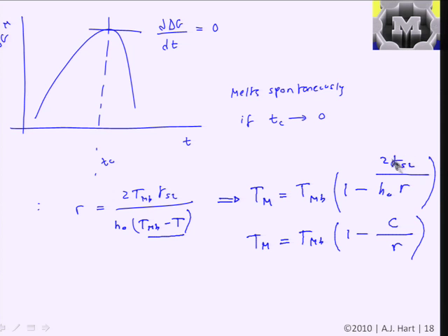Also, the value of this term increases as the surface energy of the solid-liquid interface increases, and it decreases as the latent heat, or the heat required to melt the material, increases. So if the solid requires more heat to melt, then you're going to relatively have a lesser change in the melting point, or you're going to need to give it more temperature to reach the melting limit.